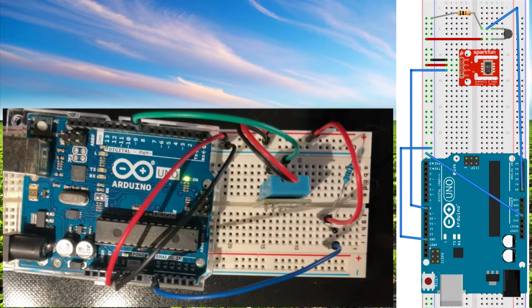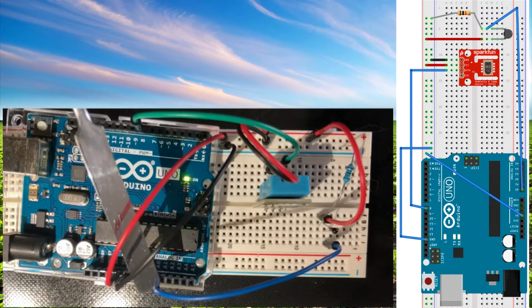The second sensor is a thermistor I got from my Uno starter kit. It came with example code including the algorithm required to convert the thermistor's analog output into Kelvin, then to Celsius, then finally to Fahrenheit. The thermistor has a 10k ohm pull-up resistor and is connected to analog 0 on the